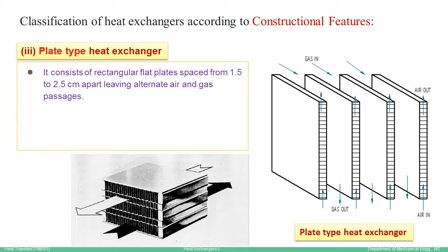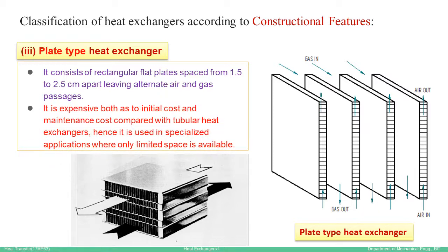This possibility calls for the most expensive method, both in terms of initial cost and also maintenance cost, because if any sediments or fouling occur inside this, it is very hard to maintain, and usually the initial cost is also high. Because of that reason, they are not used always, but wherever there is a space requirement, when you want to exchange the heat with minimum space available, then in such cases these plate type heat exchangers are used.